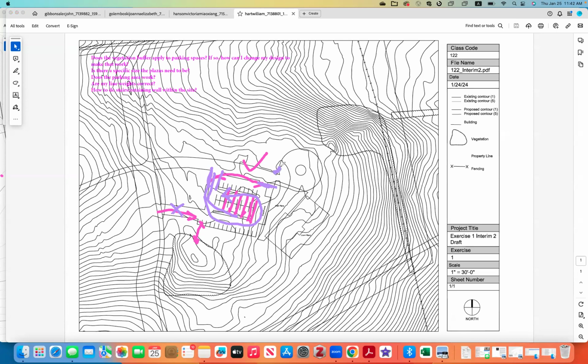And around this corner, you still have a lot of space in here. And you can see if you can actually move this a little bit lower, okay? Then meaning that you are shortening your road, reducing your paved space, and you're not getting into the steeper area. So that's a good move if you have space, okay?